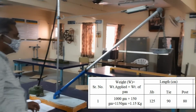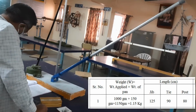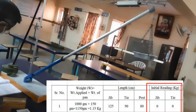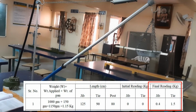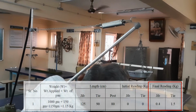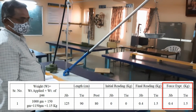So note down. Then, experimentally, the force acting on the jib and the force acting on the tie. On both members the initial reading is 0, and the final reading after applying the load is 0.4 kg on the jib and 1.5 kg on the tie.